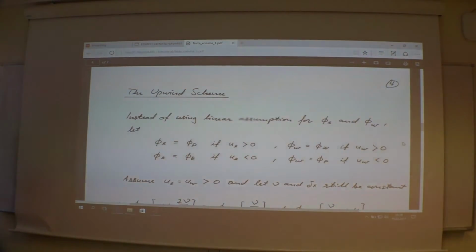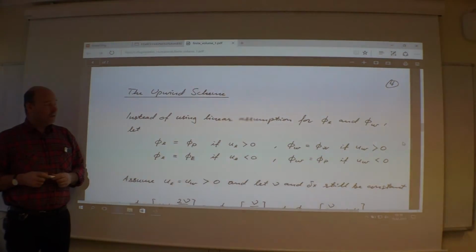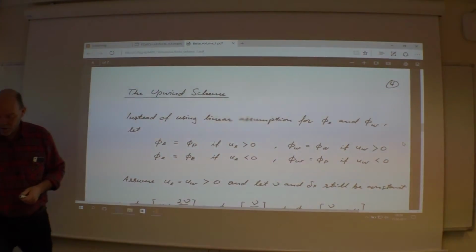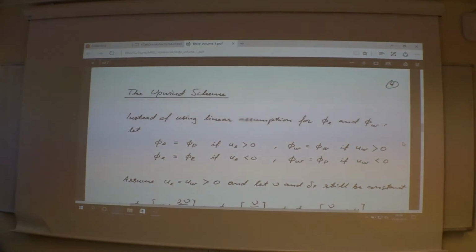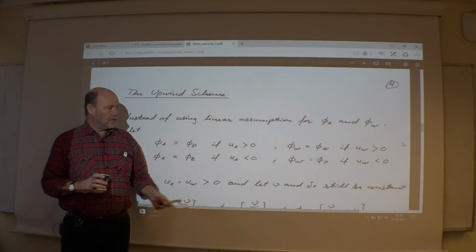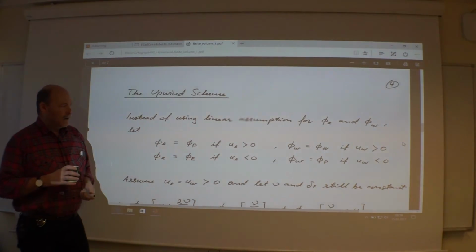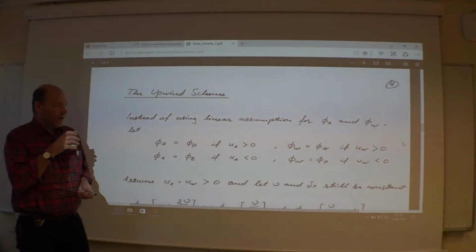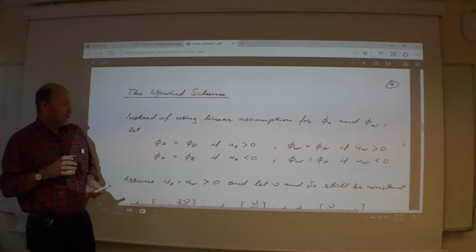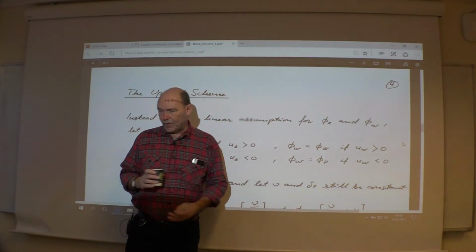But in the early 80s, we didn't have many computers, so to find a solution at all, they made it simple. So Patankar jumped instantly to the first order upwind scheme. So the classic upwind. Just depending on the direction of the flow, is the information traveling to the left or to the right? That is the question, and then you define this value on the eastern border and the western border of your control volume.